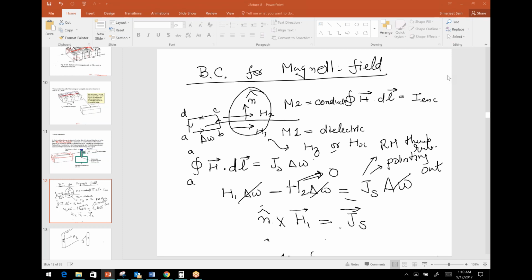Those waveguides are about 100 micron thick of silicon material, and normally they'll either put it on a Pyrex glass or they'll float that waveguide in air with some supports around the side. So it again depends. The material used depends a lot on the frequency you're operating at.